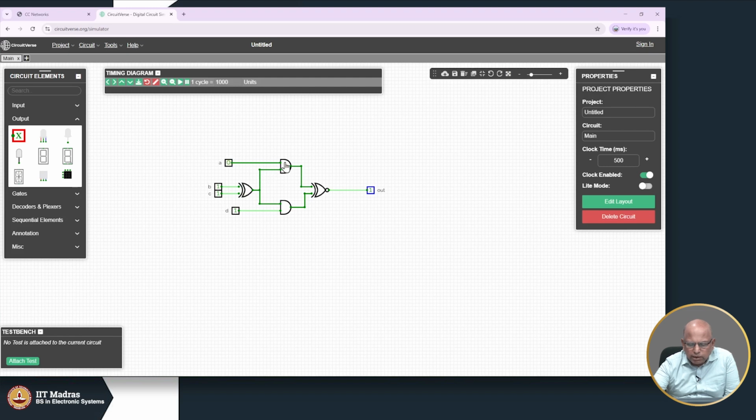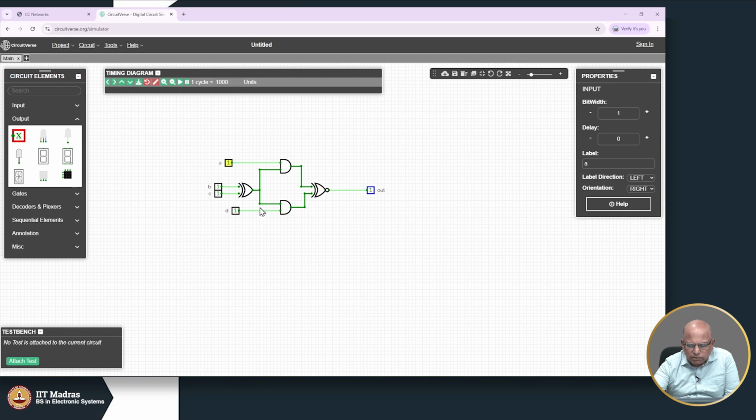And in order to propagate this further, I have to use 1 here. Okay, only then it will get propagated. And in order to propagate this further, I have to make this a 0. So this, according to us, is a test vector for a stuck at 0 fault here. Okay. So how do I prove that?